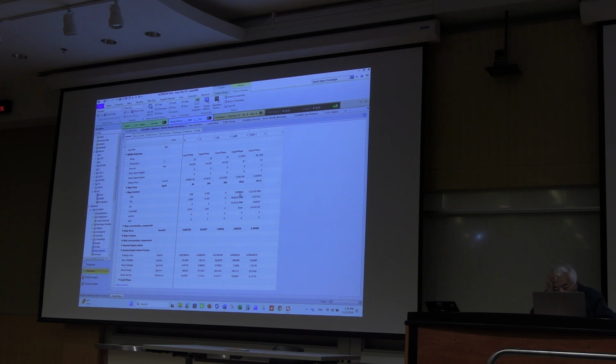For your open loop, you should not get an ACN product with no safety margin, just exactly 0.9987. Once you close the loop, this mass fraction will drop. So for 0.9987, you could get 0.9997, some safety margin. That's important.